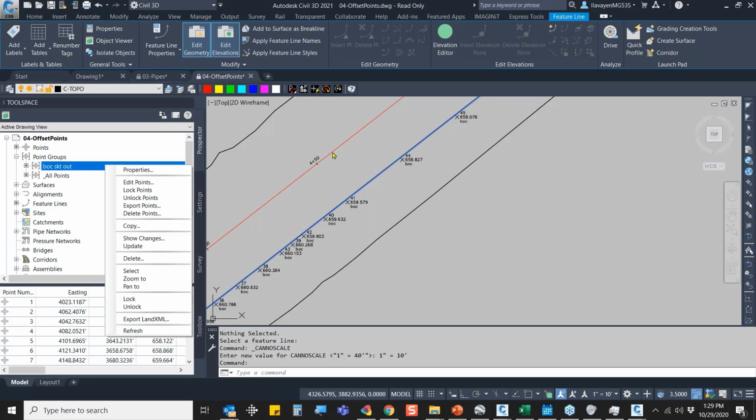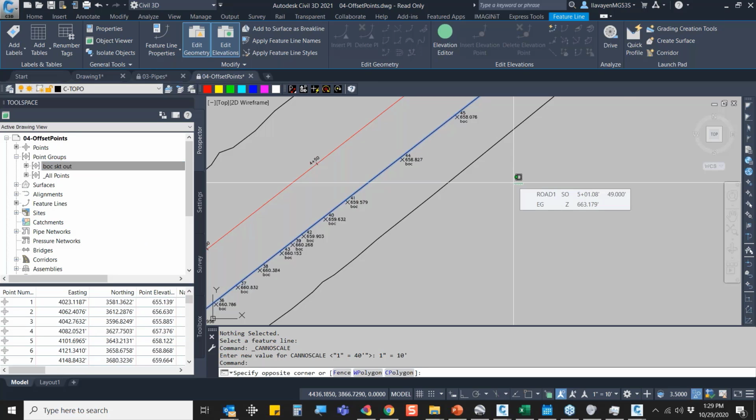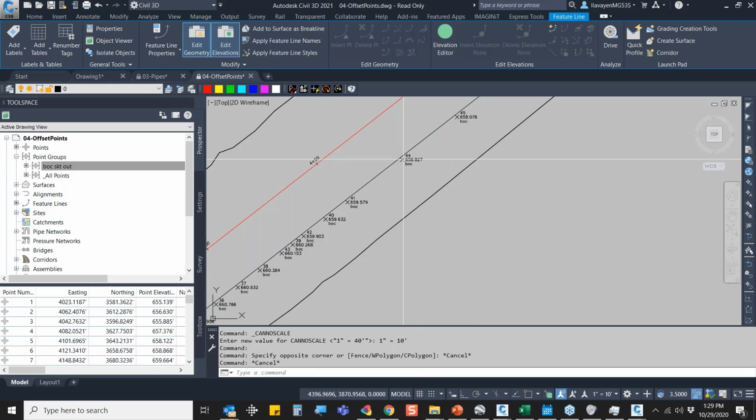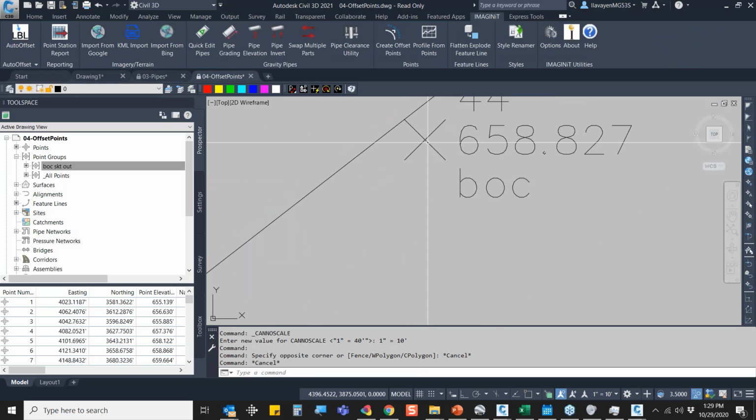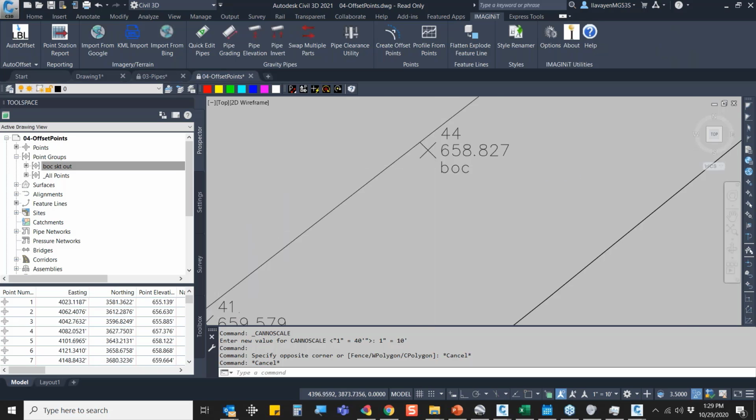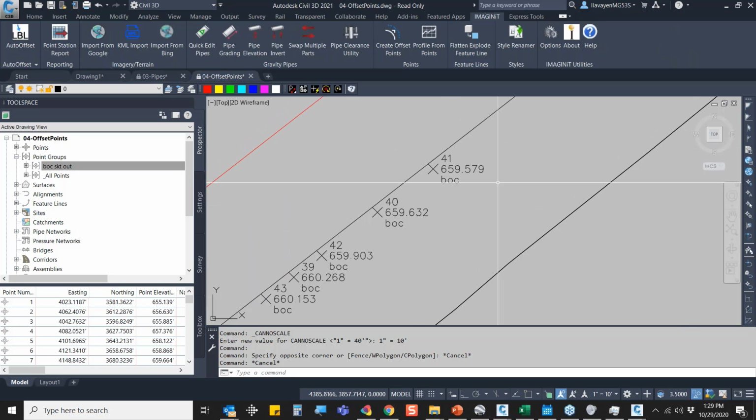So there are different ways of creating that stakeout instead of trying to create points by line. Yes, we do have very similar options from within the software to create points based upon line work, but this just is a little bit more user-friendly. And more specifically here, I also chose to give it an offset. Please note that it's not on the line, it's a foot off of it. So for some of my clients that have been wanting to do stakeout at an offset of an existing line work, there, bam, there it is. I think it's really, really nice that I can run through something like this.